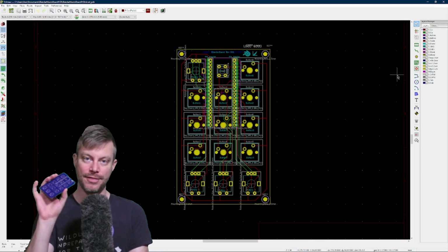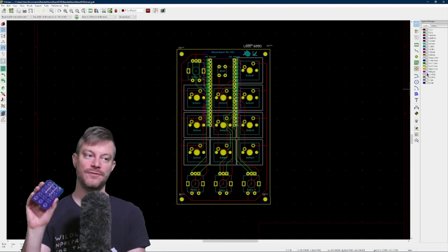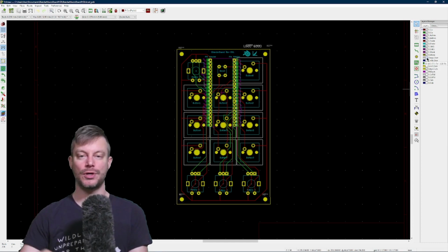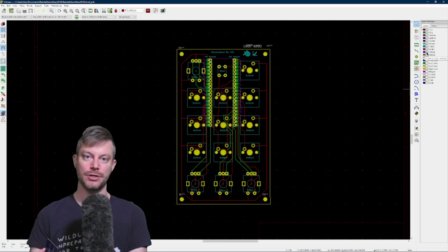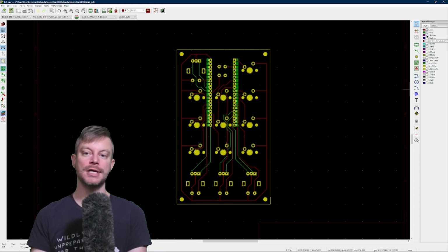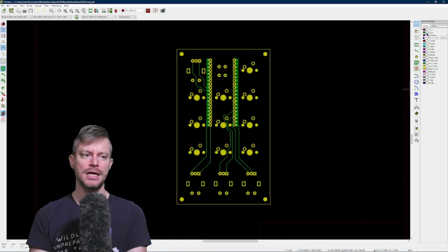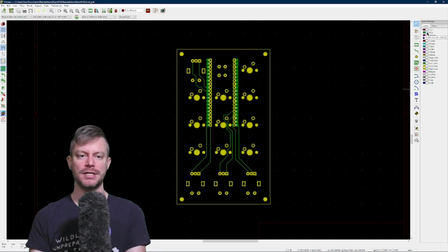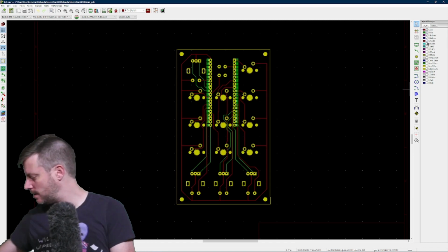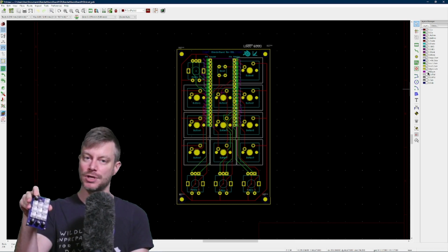Everything on this revision, on this board, takes its power from VBUS, which supplies 5 volts DC. The ADC pins, even though you can go code-wise and say, treat these as standard digital GPIO pins, just treat them exactly the same as all the others, they max out at, I think, 3.3 volts. It's either 3 or 3.3 volts. So if you supply them more than that voltage, then basically they just leak between the pins. So what was happening was I was turning the knob on top, which was intended to navigate frames along the timeline.